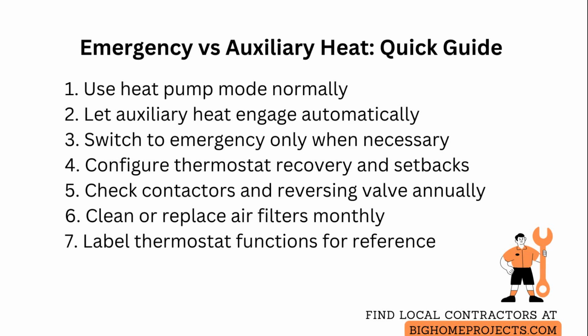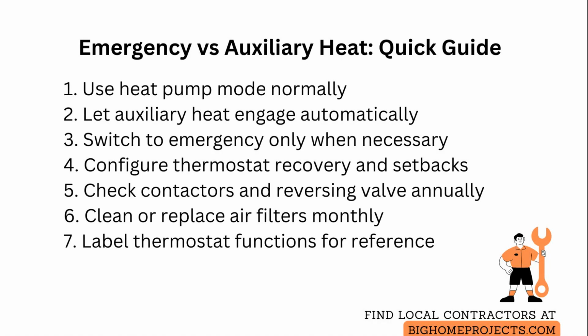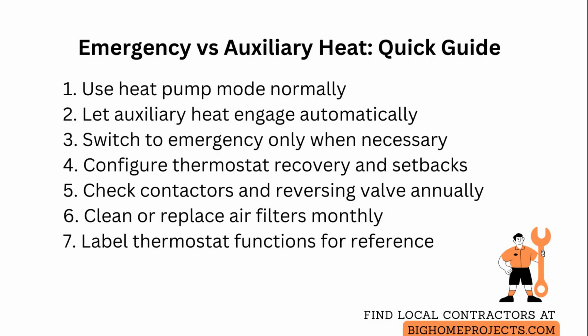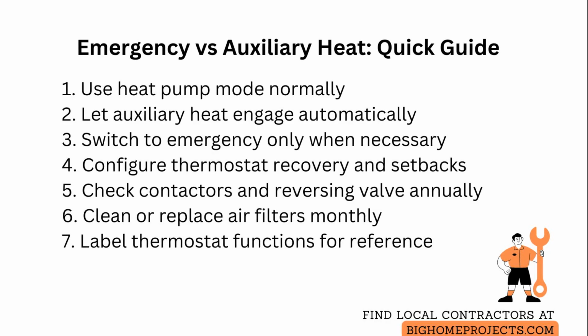For maintenance, check contactors, reversing valves, and outdoor coil defrost function each fall, and clean or replace air filters monthly during the heating season to reduce reliance on auxiliary heat. If you are uncertain whether your system uses electric strip heat or a gas furnace as backup, consult the system data plate or installer documentation and label the thermostat functions for future reference.